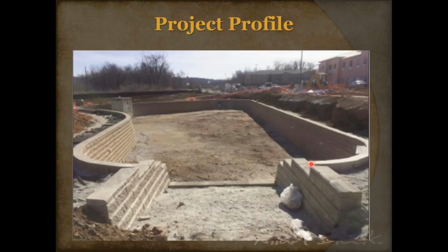And then I'll give you the final shot. It's still under construction here. They're bringing in the soil media, but you can see after the 5 courses, now they give you some overflow. They brought in some of the piping and stuff like that. You saw the one major pipe coming in on the one side here. Notice how they're constructing the berms above the wall. What I want to point out is they also have an overflow point right here, which is at a similar elevation to the berms. So if it does come up, they've got that overflow coming in. Again, there are a lot of logistics when you're talking about bioretention ponds, because you have to look at the flow requirements or the water requirements.